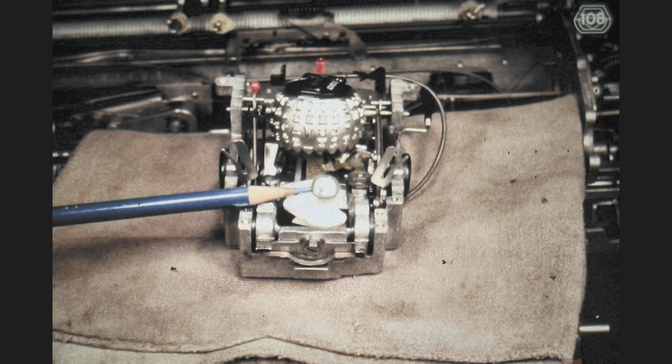If we fail to keep them properly lubricated, we end up with worn bearings for the print sleeve. The effects of this wear vary from escapement malfunctions all the way up to poor alignment. While it is only a minor job to replace the tilt pulley sector or the print sleeve bearings, if and when you can get them, it becomes a major job if you have to replace the whole carrier frame.